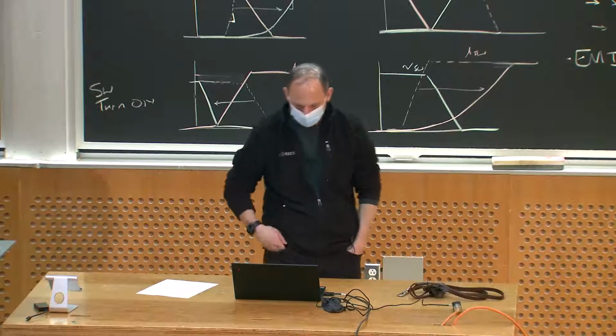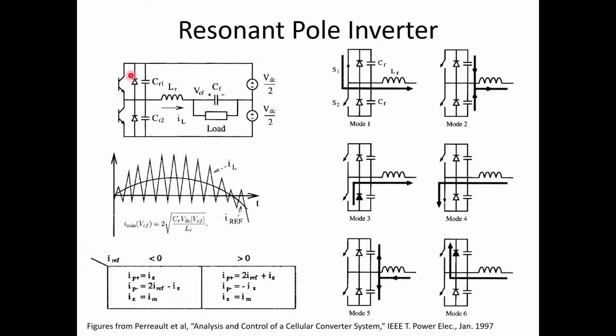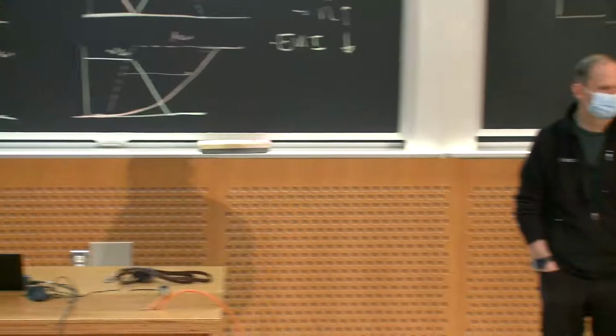And what we can see is, here's my switch, and I'm showing, you know, like an IGBT or a bipolar with a diode across it, but this could be a MOSFET, okay? And each of the two MOSFETs in this bridge leg, this is clearly a bridge leg or half bridge, has a capacitor across it, okay? So what does that suggest to you about what kind of soft switching I'm going to be doing? Got capacitance across my devices.